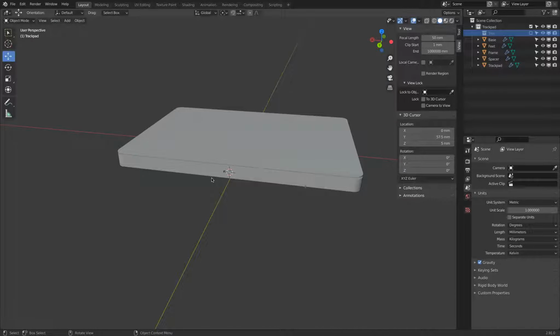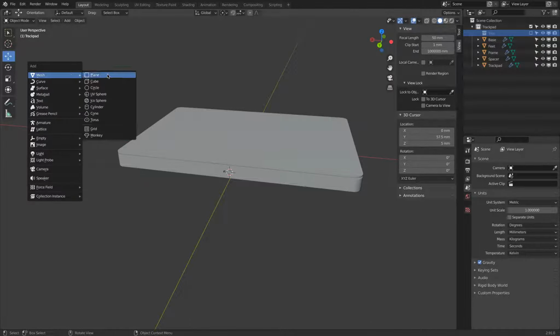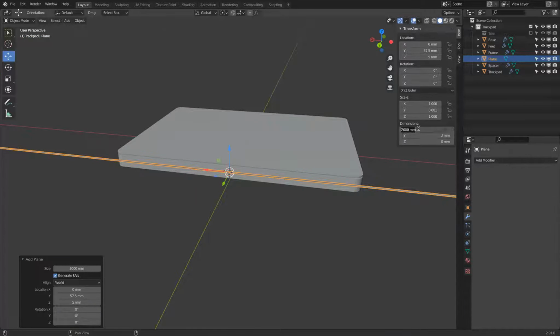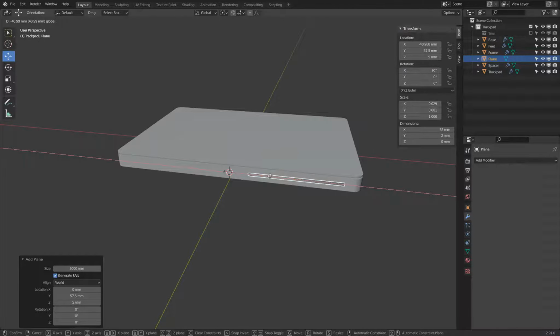Let's make the opening for the antenna. The antenna object basically has the same height, the same edge rounding, but is 58 millimeter wide. Okay, so we start with a plane. Again, this Y is 2. And then this now is 58. We rotate this. Can bring this over.